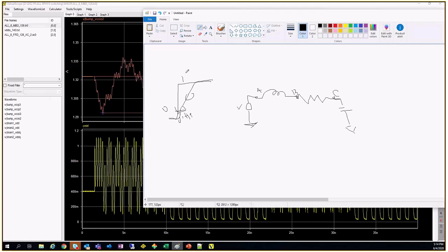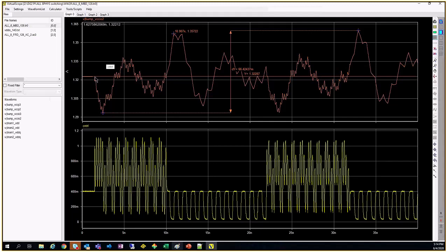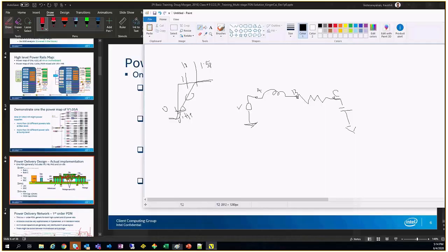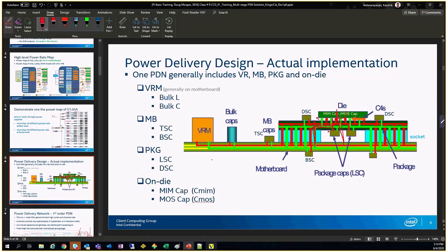So you are expecting your one value to come here, let's say at 1 picosecond, but it's becoming 1 only at 1.5 picosecond. Why? One of the biggest reasons will be this droop over here, because of the time it takes to charge. 0 to 1 is affected by how fast you can provide that voltage without much of a loss.